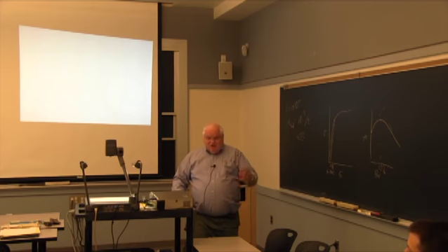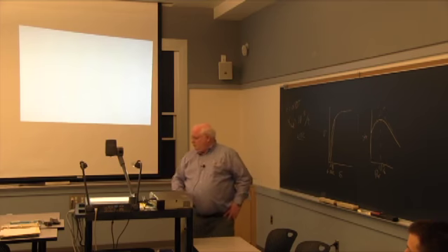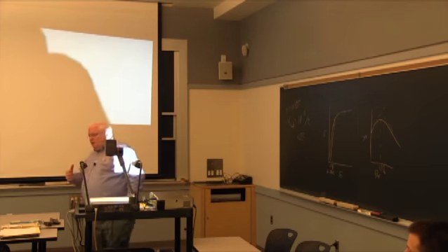Okay? You don't see 2-inch layers of carbide bonded by a brazing joint to a piece of steel, or diffusion bonded or anything else. This is just dissimilar metal bonding, and it's not necessarily diffusion bonding I'm talking about right now. And it's because of the strain energy. Same thing that I just had up here on the board. So that's not to say there aren't ways around it.